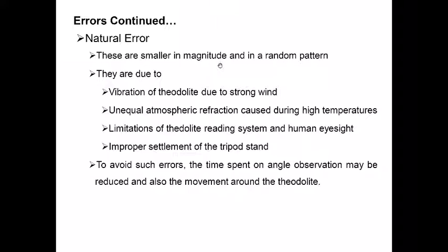Now I would like to just sum up what we have discussed about the theodolite. When you set up a theodolite above a station point, you have to carry out centering, leveling, and focusing of the eyepiece so that you remove the parallax, and then we can take the angle. This instrument allows you to calculate horizontal angles, vertical angles, horizontal distances and also vertical distances. We will talk about how we can measure horizontal distances using the theodolite, and also how we can measure vertical distances as well. So this is it for this lecture. I'll see you in the next lecture on the same topic. Thank you.